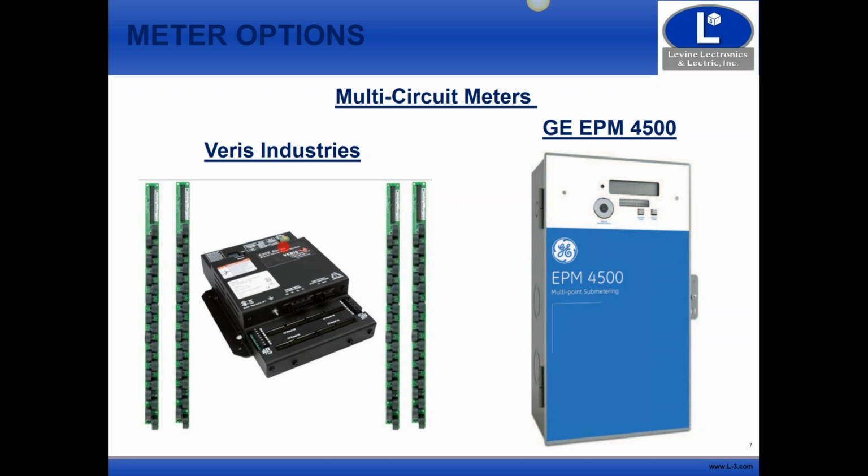And remember, we've got to go in and program this. So we've got Modbus memory maps for each one. If it happens to be a meter we haven't used yet, we've got to build those from scratch. We have to do the commissioning on site and make sure that we're reading from each one, getting the data into the meter and into our data collection.